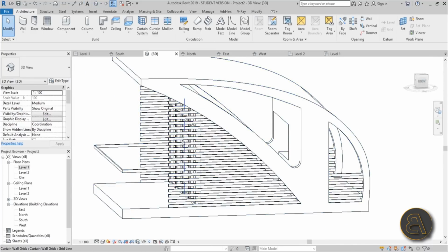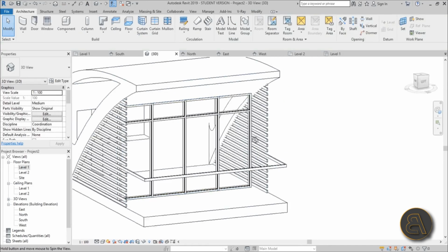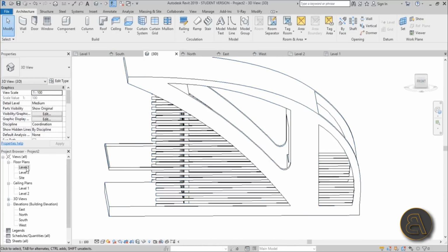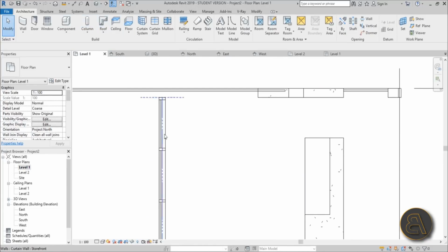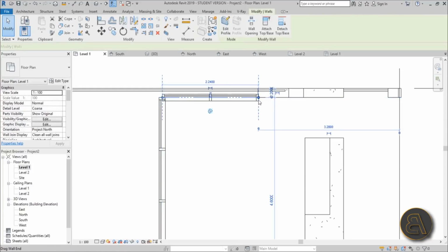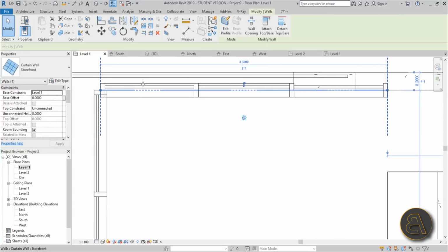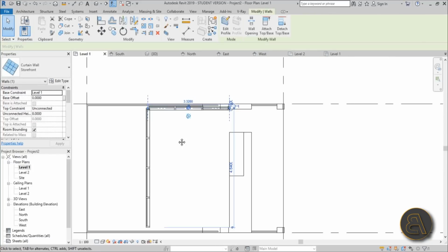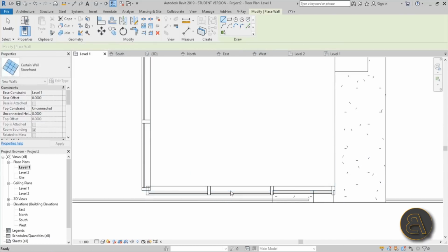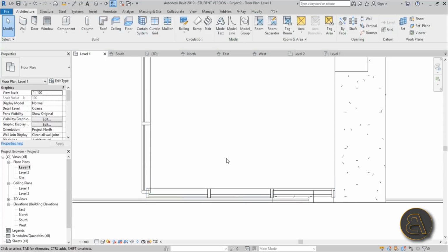Now let's add a door over here, but before we do that, let's continue. This curtain wall should be going to this side, because this wooden part is only cosmetic, it's actually hollow, so let's add a curtain wall and close this whole thing off. So for that, just go to level 1, and again, curtain wall, and just attach it all the way to this wall over here. Maybe move it a bit closer to this wooden element, and do the same thing here. So just go to this thick big wall, and again, maybe bring it in like so.